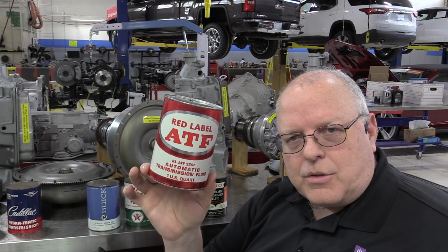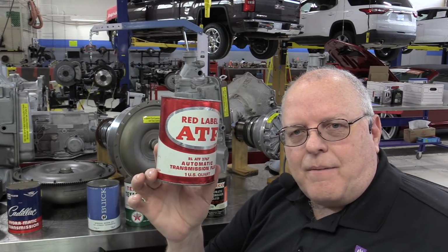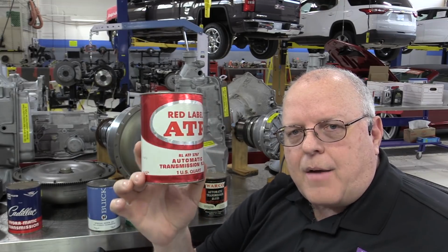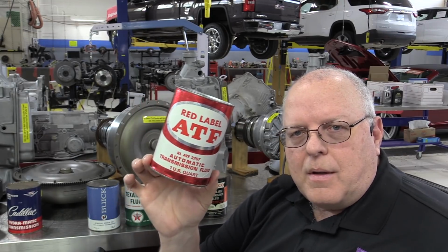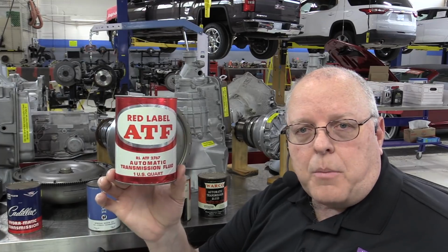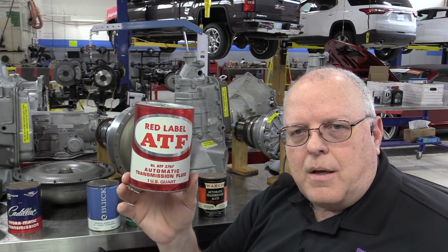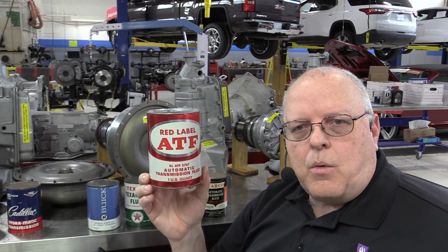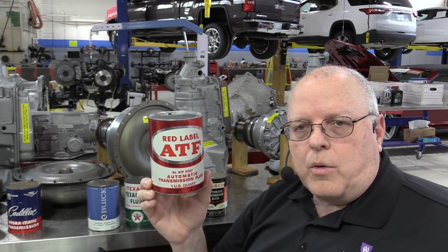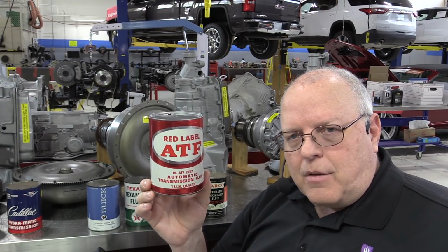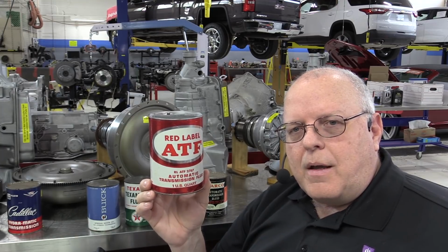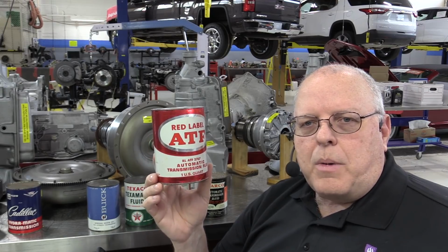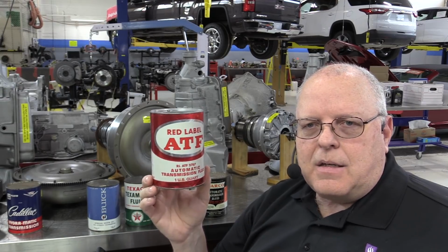So remember, I told you at the start of this series that transmission fluids were not red until a certain point. Well, the aftermarket fluids appear to have come up with the idea to have red fluids, because in the next fluid after Type A Suffix A, which is the original Dexron fluid, in the fluid specifications for that fluid, it doesn't require it, but it recommends that the fluid color be red to aid in leak detection.